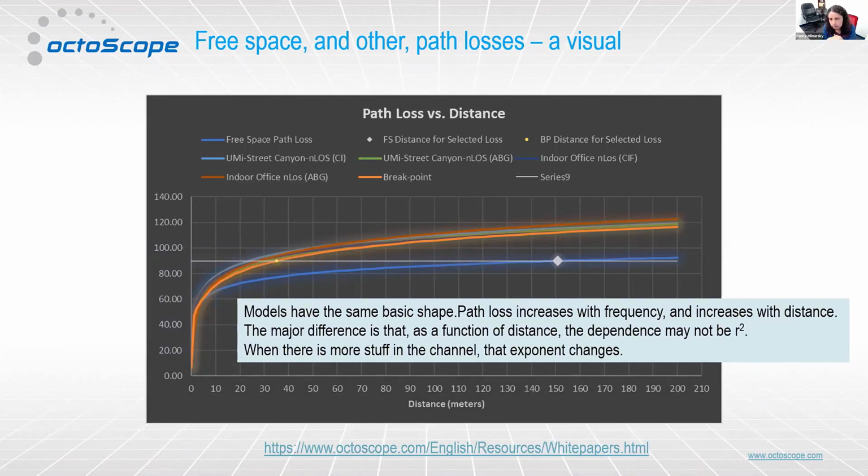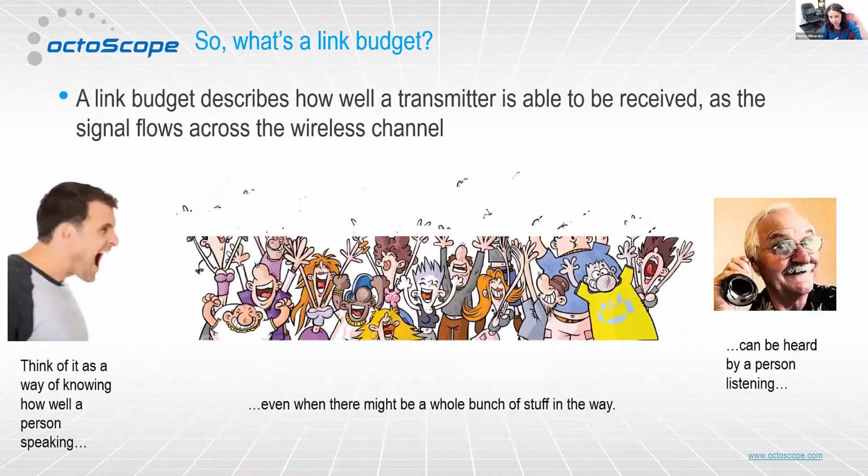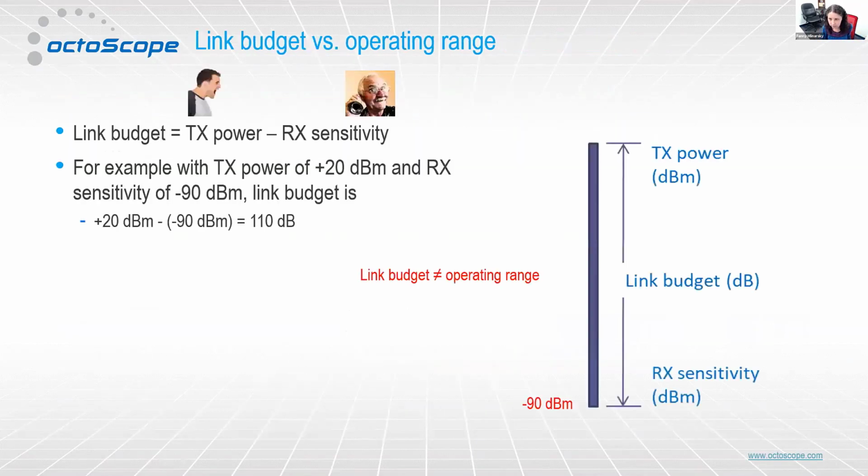When you're doing the full range of your link, the important thing is that you can get, like Lee was showing, the link budget from saturation to disconnection to below your sensitivity. If you have that full range in the test bed, you can effectively test indoor and outdoor links. That's true in the Octobox. Our attenuators have 90 dB of range, and they will disconnect even for GLT, which is the most challenging to disconnect at lower frequencies. So yes, it's usable for indoor and outdoor links.